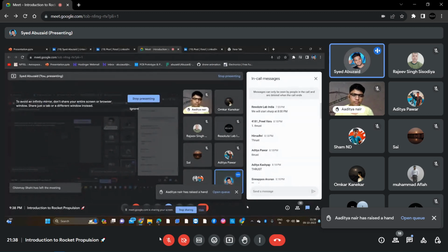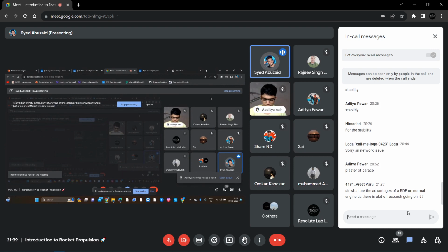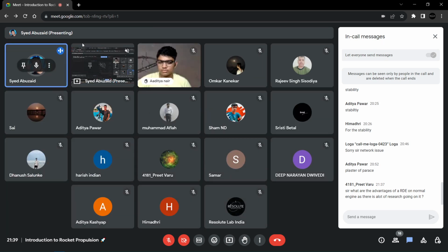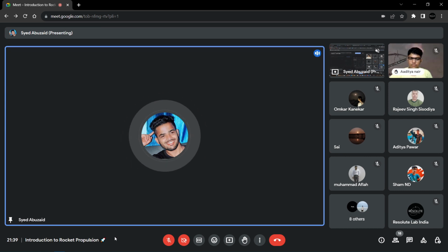No, I'm just telling you, if you're working on a competition, I have already worked on one, the CANSAT competition in Texas. I applied for that and we visited via our university. If you're facing this issue, just look at the throat area of your nozzle. The throat area of the nozzle passes the amount of mass through it, and that produces the thrust. If the diameter of your holes is very small, it flows a small mass, and that produces a small amount of thrust. So you need to analyze the exact number.